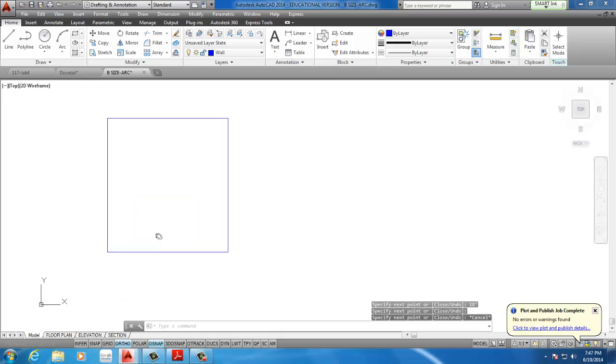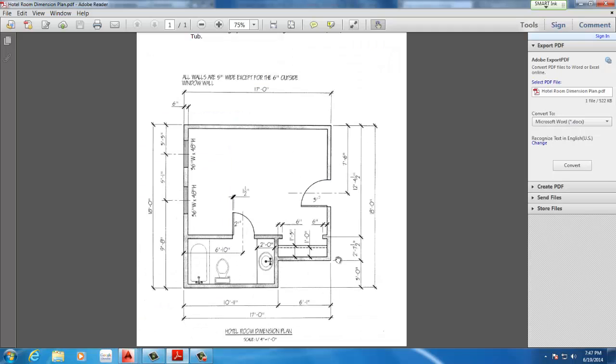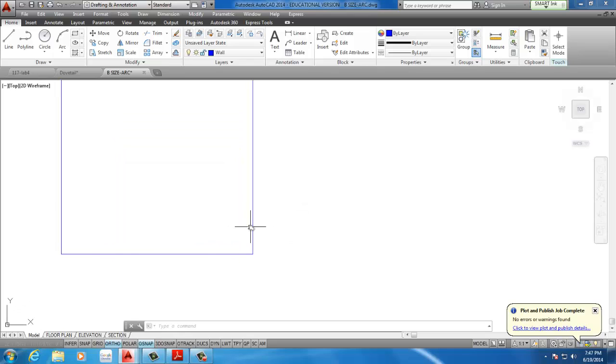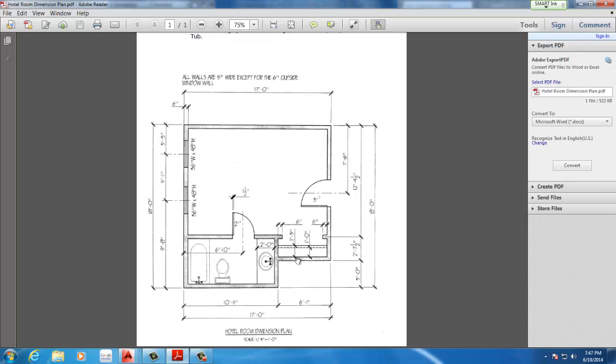Now these are exterior walls, so they will be 6 inches. So when we do offset, they will be 6 inches. But before we do that, I would like to make that cut right here. To do that, there's a few simple ways. I can offset both these lines. The bottom line I will offset 3 feet, and the second line I'll go 6 foot 1 inches, because that's from the exterior to where the opening ends.